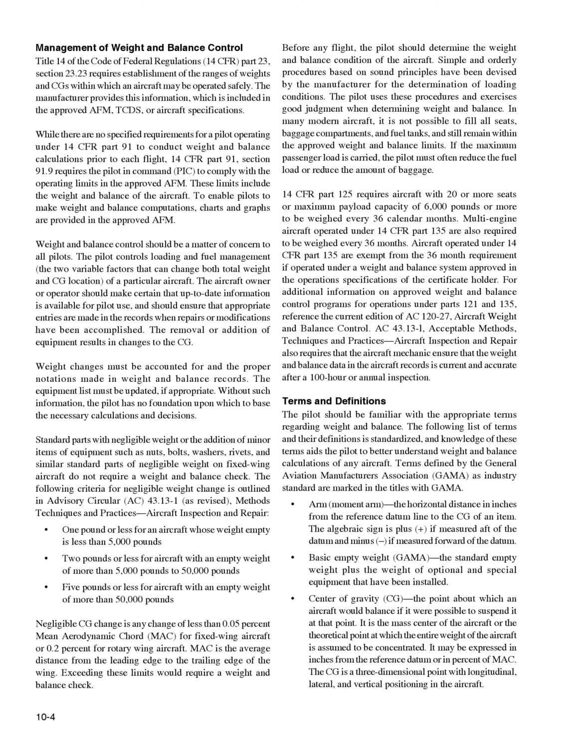Negligible CG change is any change of less than 0.05% mean aerodynamic chord, MAC, for fixed-wing aircraft or 0.2% for rotary-wing aircraft. MAC is the average distance from the leading edge to the trailing edge of the wing. Exceeding these limits would require a weight and balance check. Before any flight, the pilot should determine the weight and balance condition of the aircraft. Simple and orderly procedures based on sound principles have been devised by the manufacturer for the determination of loading conditions. The pilot uses these procedures and exercises good judgment when determining weight and balance.